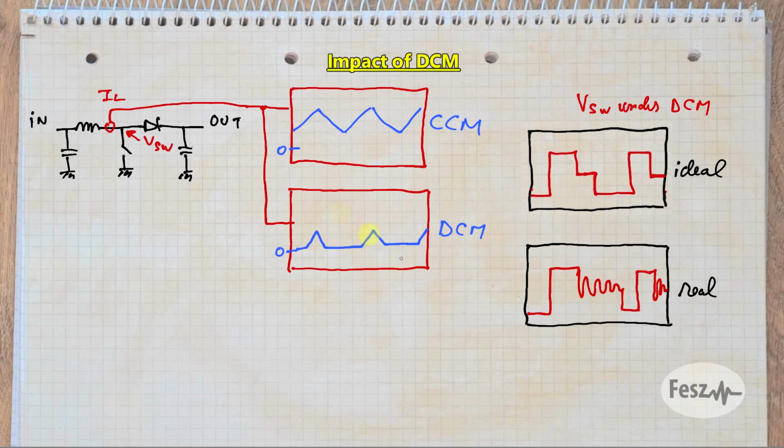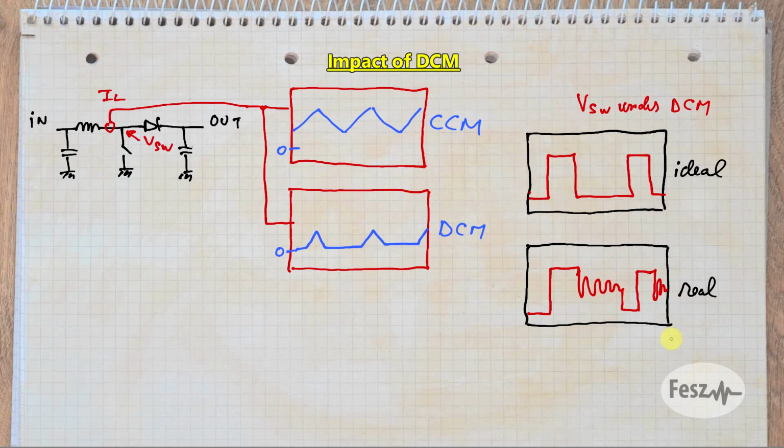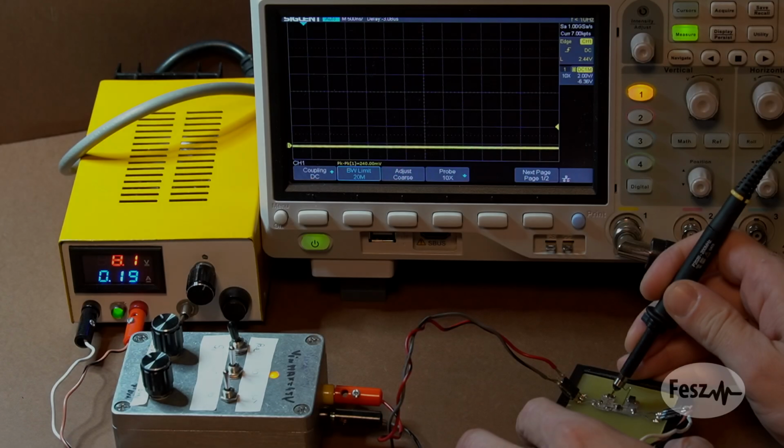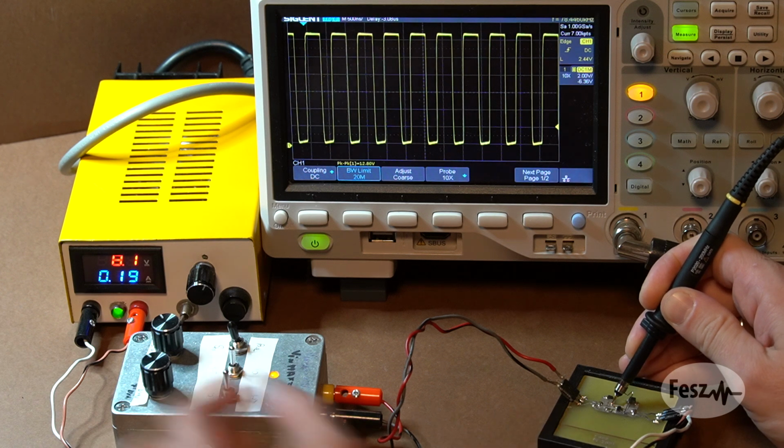Once the diode no longer conducts, the inductor with the various stray capacitances forms an oscillator. And it oscillates until the next switching cycle starts. This is usually oscillating at a higher frequency than the converter, but lower than the ringing we previously observed. Therefore, it can still be quite problematic. So we can also have a look at this behavior.